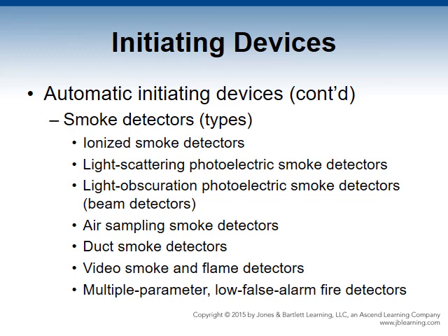Their earlier detection helps protect against unintended discharge of suppression agents. Air sampling systems are installed where concealed detection is important, maintenance access is limited, or critical processes cannot be disturbed, such as historical buildings, production facilities, and textile mills.